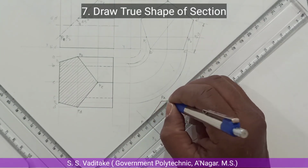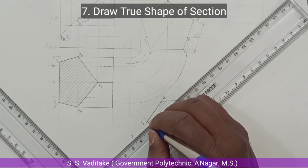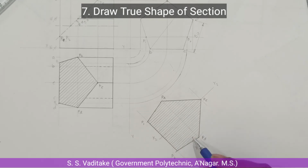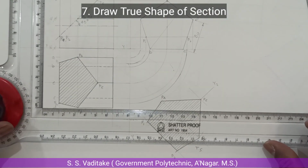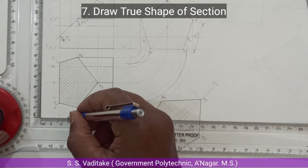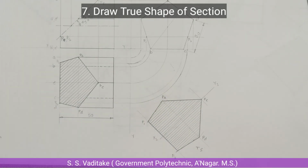Now, as it is a sectional view, hatching lines should be drawn. So all hatching lines are completed. Now label it as the true shape. Do the dimension as the length of the axis is 50 mm.